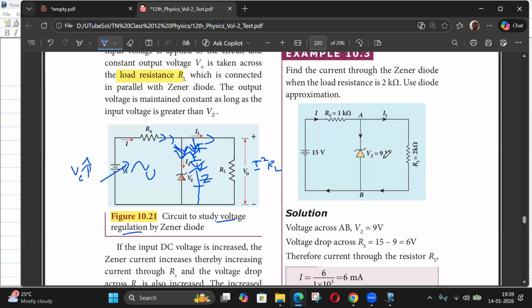So here the thing is 9 volts. So the maximum voltage across this thing will be approximately 9. So the current here, I can fix it. In the sense it's fixed. There will be 9 volts by 2K, that is 4.5 milliamps.